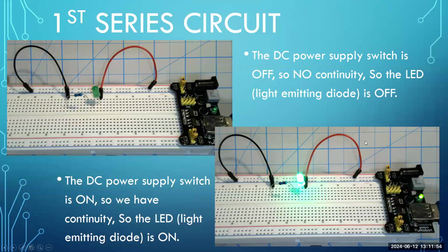If we take a look at the lower right illustration, you will see that the board is now energized because the board has an LED of its own that will show that it is in the on position. It's turned on by virtue of you pressing down this latching switch. Once you press down once, this will light up and electricity will be allowed to flow through these power rails in the circuit that I've built and that you will be building in just a moment.